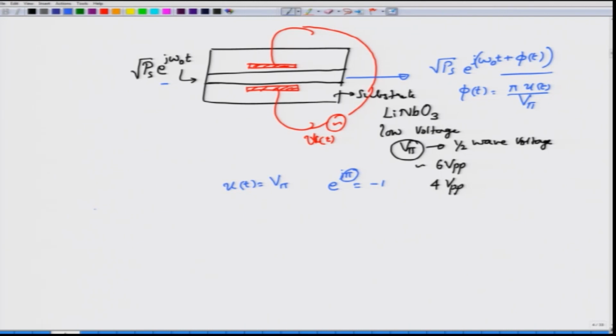Now, what can we do with this phase modulator? Let us consider the simple modulation format called binary phase shift keying. What is this binary phase shift keying? It means that if there is a bit 0, then you transmit a cosine wave of some phase. So, let us say this is the time interval called the signaling interval. This is the interval over which you are sending a bit 0 and then you want a cosine wave to go something like this.